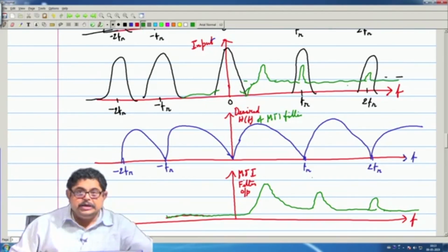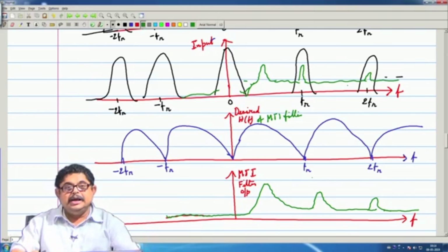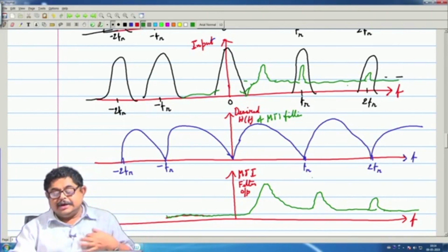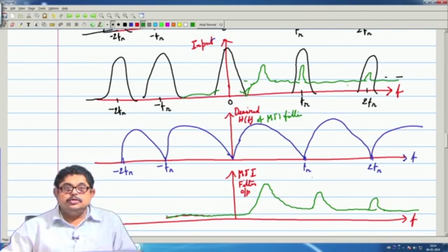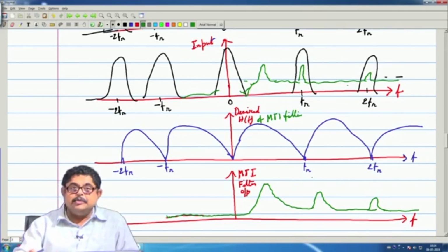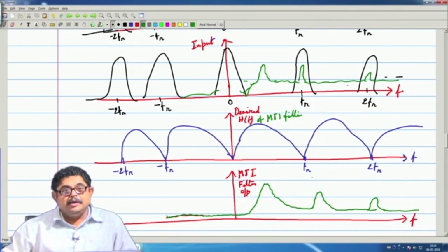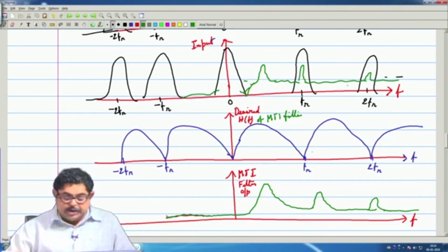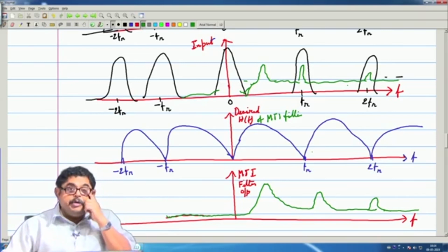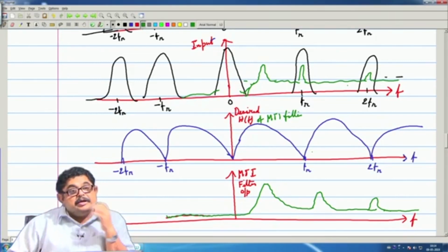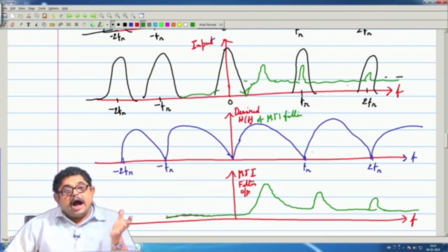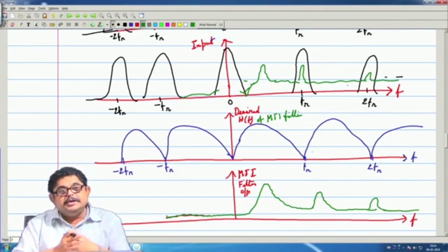Okay. So, we will see that the delay line canceller that we have discussed has this type of response. Also I have mathematically derived that it is a pure sin(pi f dt) type of function. So, that can do this Doppler removal, but in the process the blind speed etcetera has come. Now, we will discuss various implementations of these MTI filters, and finally, we will compare them, because how much clutter is getting removed I am qualitatively saying, but we should require some figure of merit for that.